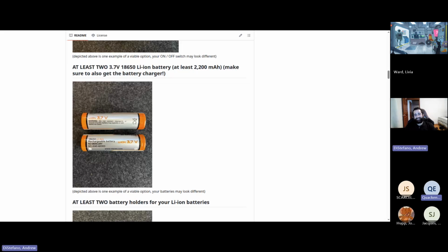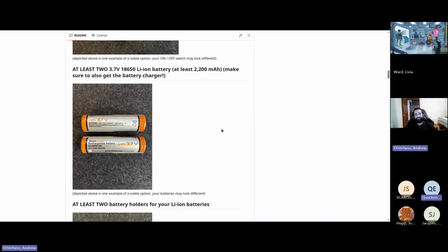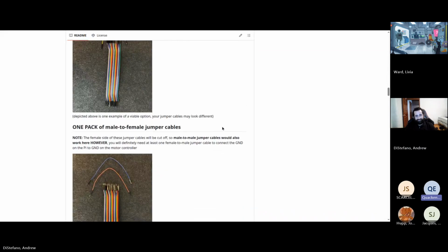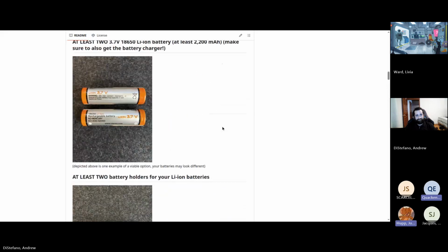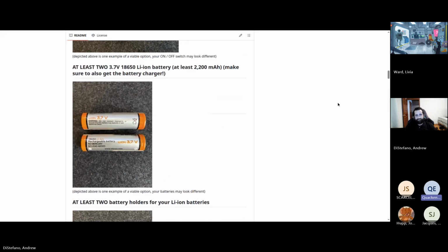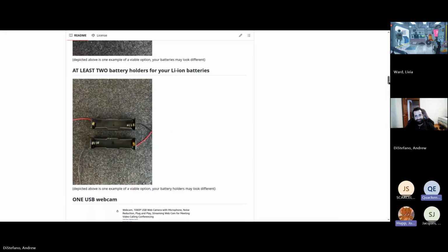But you also need the current too, which you get by putting the batteries in parallel. So you just need the right series. But I guess my concern is, I've done some power budget calculations, like with how much current you would have to source at max. You're running the motors full duty cycle.